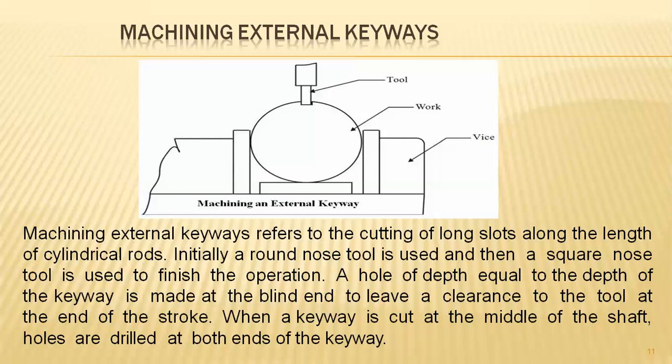And if you have to increase that 6 mm drill bit towards 8 mm, then the boring activity is the preferable activity on work parts that already have a hollow section, in order to enhance, or increase, its diameter. And even for special working additions, nothing but stepwise cutting and stepwise maintaining of different diametrical strategies, internally or externally, to obtain diametrical deformations as per our requirements, our drawings, and our standards.